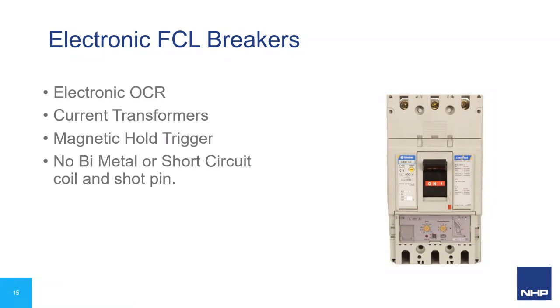Until this event, the contacts will remain latched closed, and this is very important to understand. The OCR measures according to its clock speed or its scan rate. Now, the Terasaki range of MCCBs and ACBs have a scan speed of between 2 kHz and 4 kHz for the later models. This means that the OCR scans between 40 and 80 times per electrical cycle, per 50 Hz power cycle. It samples and integrates each measurement until a number is reached in each running sequential time period